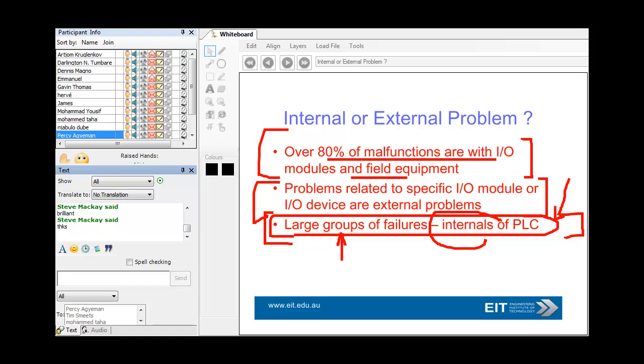The power station went on standby. Inevitably, we did the changeover to the secondary CPU, the Allen-Bradley PLC, and all the analog values froze, the whole lot. Then we had massive failure, and it was an absolute disaster.